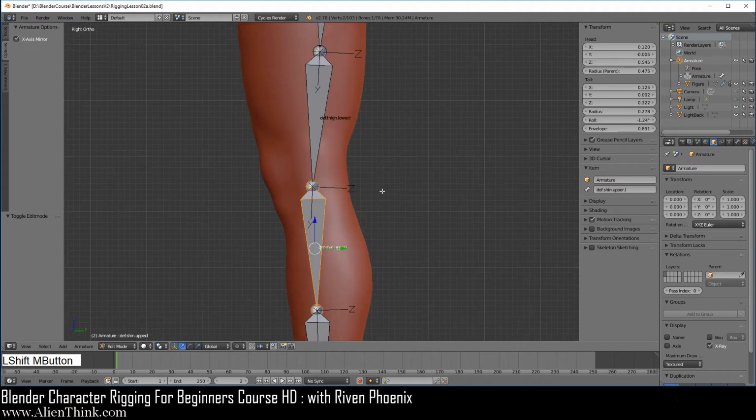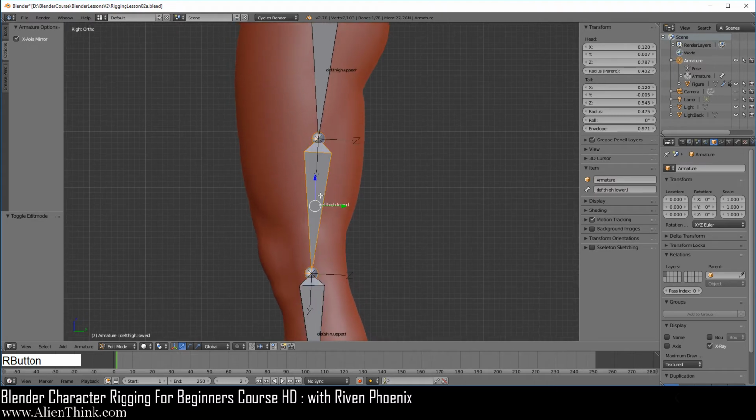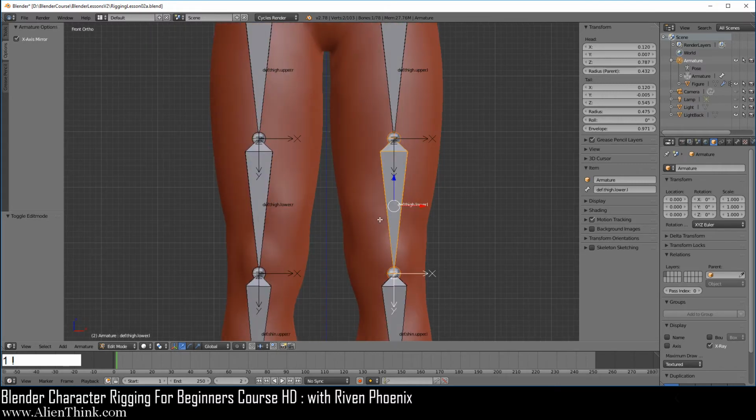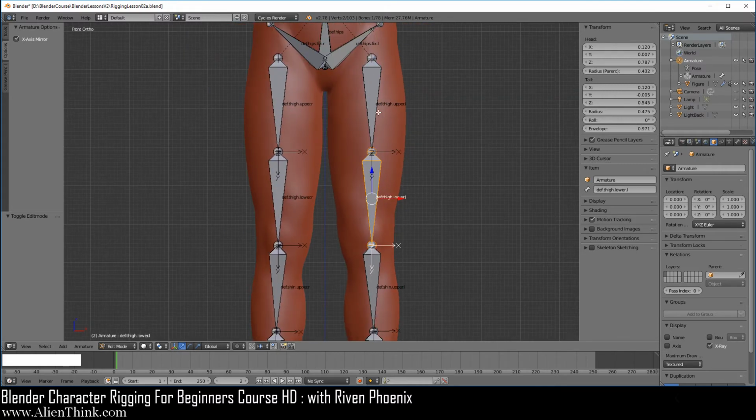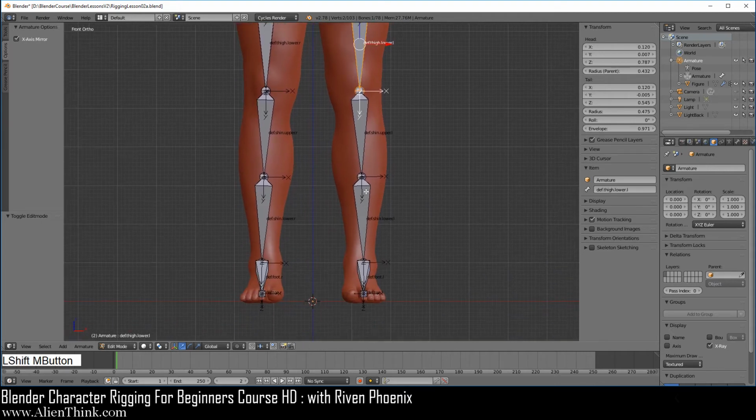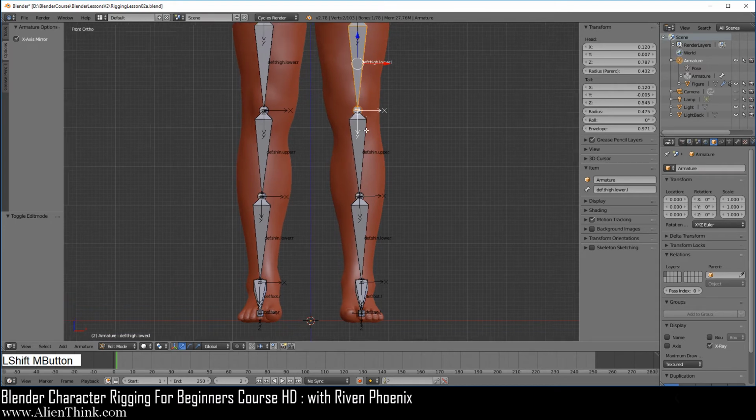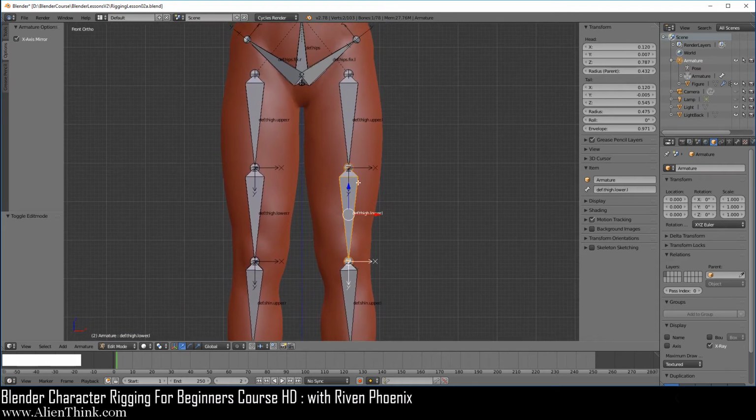Now you'll notice that if we switch to this bone over here, it'll be 0. Now why is this 0? The reason for this is because when we place this bone, we simply just went down. We never nudged it to the left or the right from the front view as we had done with this bone, okay? So this bone is going to be correct too.